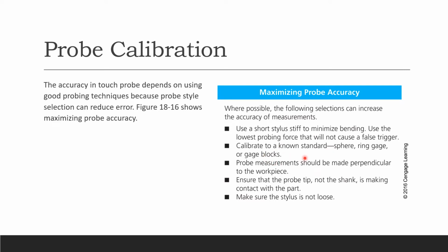Calibrate to a known standard. We do that all the time, right? Your sphere, ring gauge, or gauge blocks. In our basic lab, we use the gauge blocks.